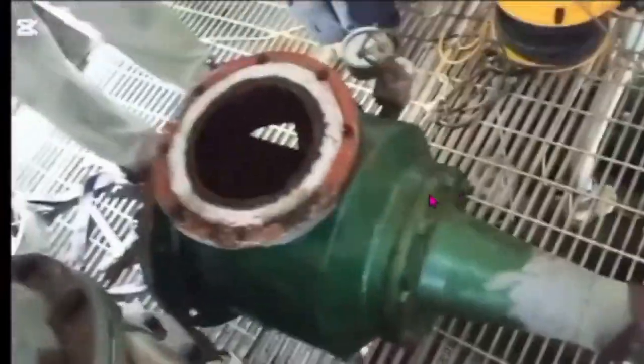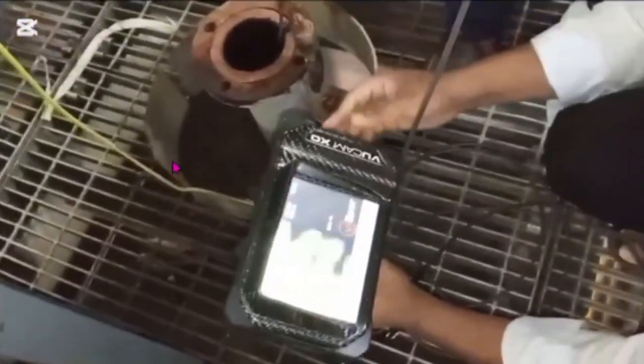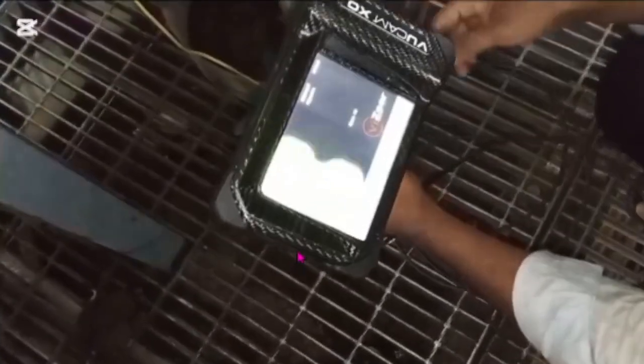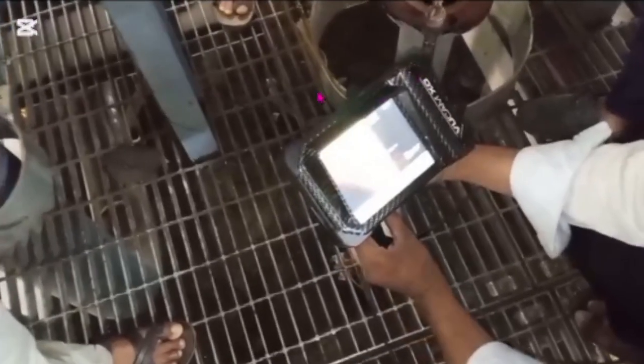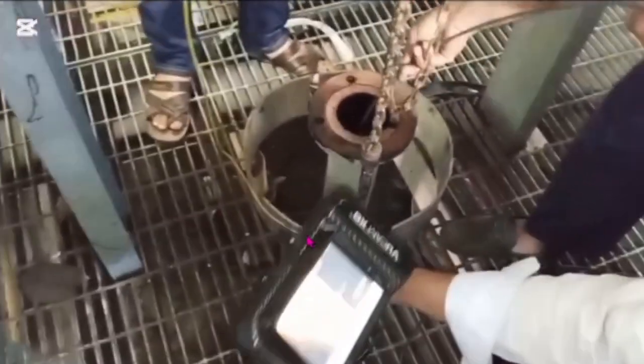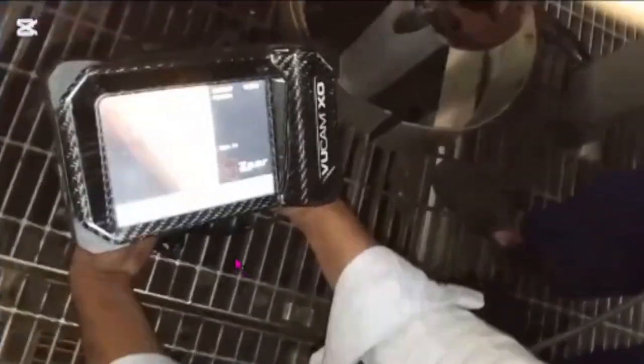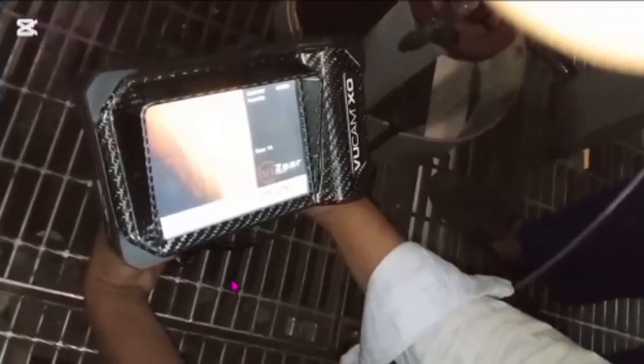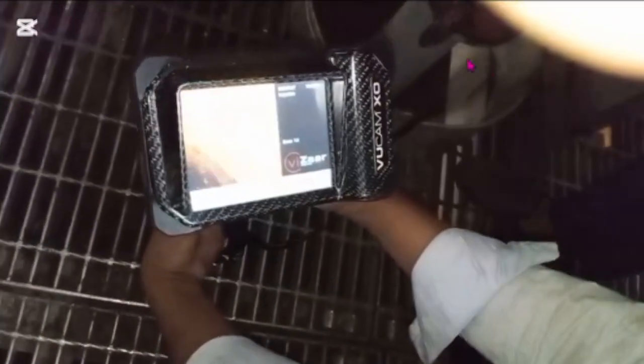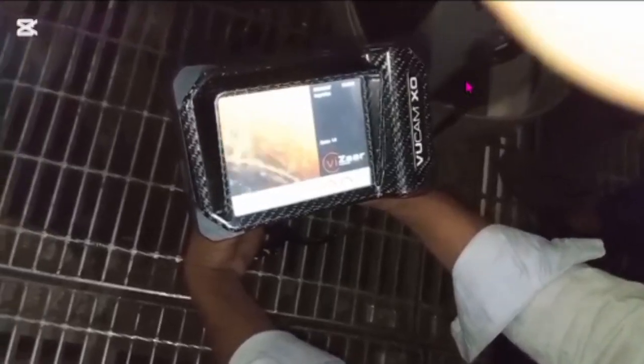You see, this is the old one, and here it is damaged also. By scanning, we measured with our sensor inside this ejector and found some damage and corrosion. So when we changed the new ejector, we also changed this line.